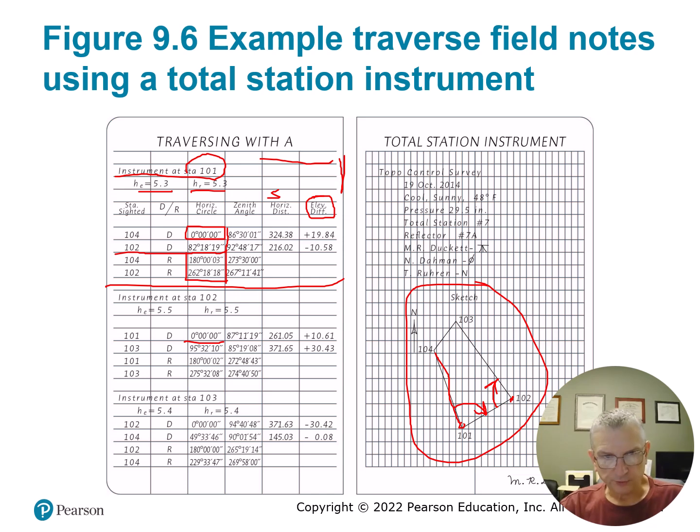And here they're saying that it's 3 seconds off on the back side, and it looks like 1 second difference because 18 is 1 second difference to 19, but you really have to look at the angle turned from 3 seconds over and realize that you're actually 4 seconds under, because that 3 seconds adds to it. You get a computed angle.